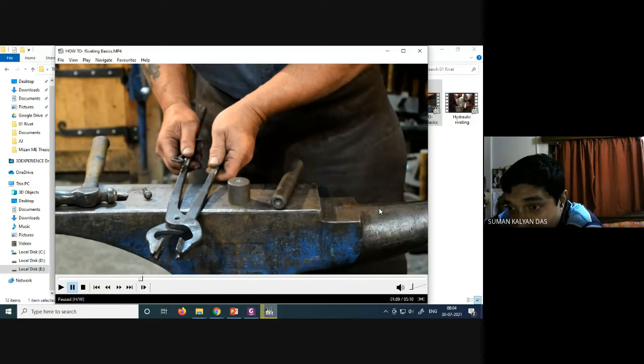Now, what are those electrical cells? Electrical cells are locally made electrical circuits. Obviously, the circuit is not made by wire, because there is metal to metal contact. So there can be local cells where electrons are transferred from one place to the other. If those cells develop due to the difference in electronegativities of the rivet material and the parent material, they will give rise to corrosion. Corrosion is nothing but an electrochemical phenomenon. If corrosion happens, it will degrade the joint.